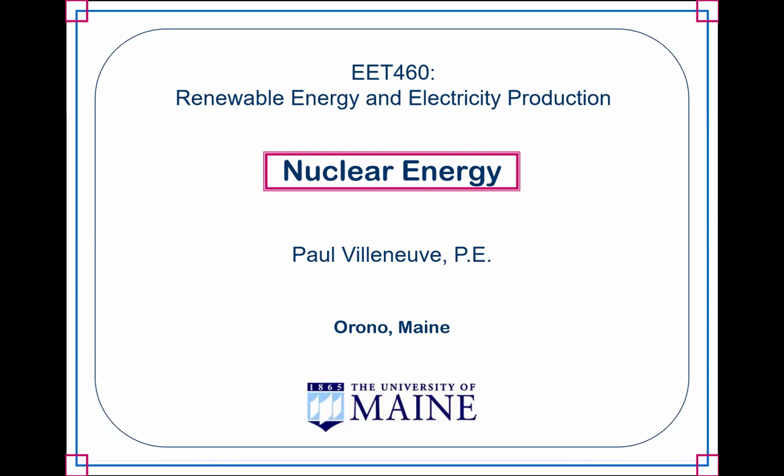Utilities, or the transmission owners or transmission operators, don't have the luxury of being able to say, we will just see what the weather looks like today, and then decide whether to dispatch the solar generation or wind generation. They have to know that it's available, because they need some forecasting ability and some ability to tell generators we're going to probably need 200 megawatts, or however many megawatts, at a certain period of time. They need to be able to feed the load that is demanded. So having non-dispatchable resources makes that a very challenging approach.